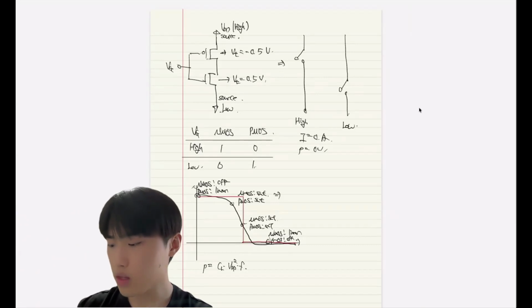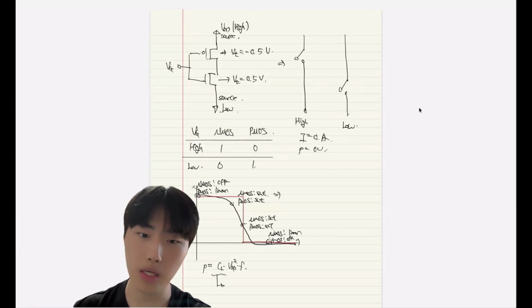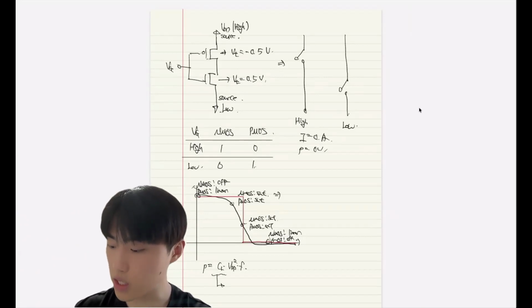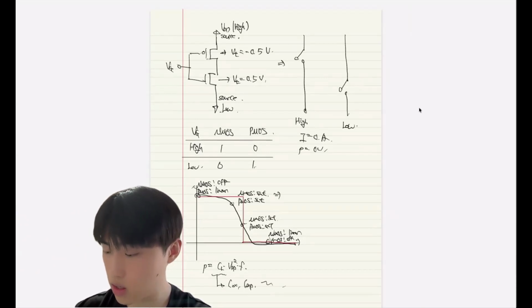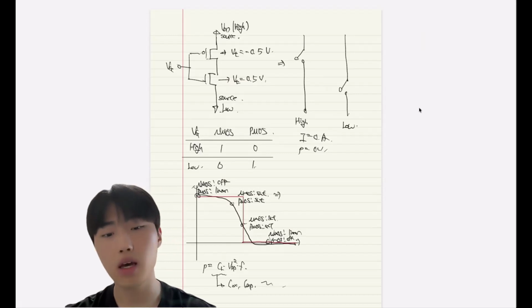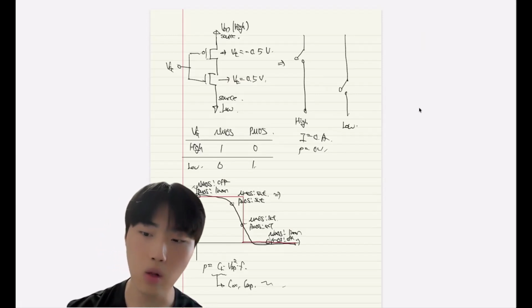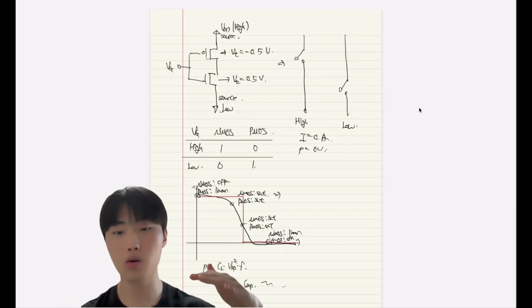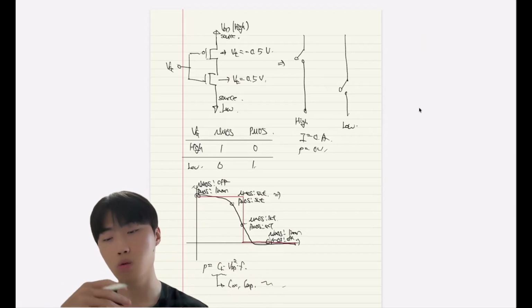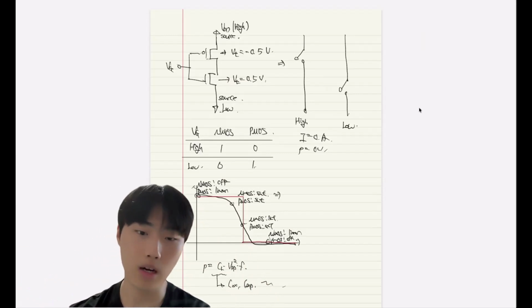In the load capacitance, there are lots of capacitances. For example, there will be C_OX or C_DP or some others. But C_OX has to go higher, because when the C_OX gets lower, the coupling between the gate and the channel gets weaker.